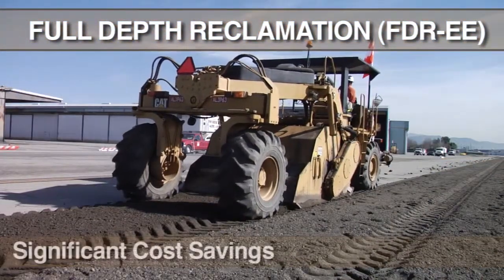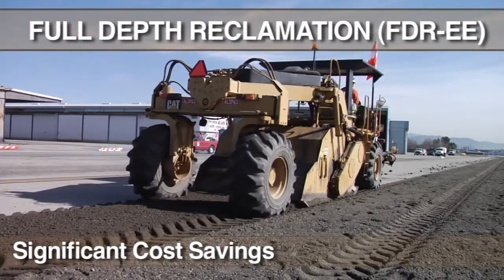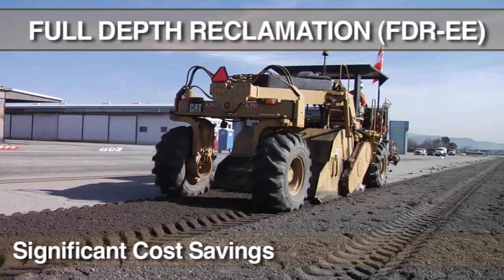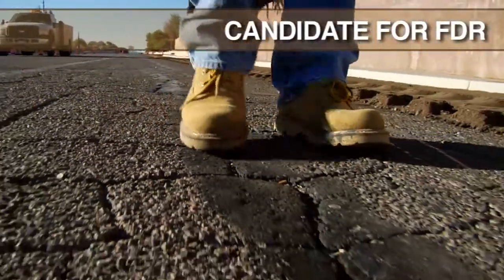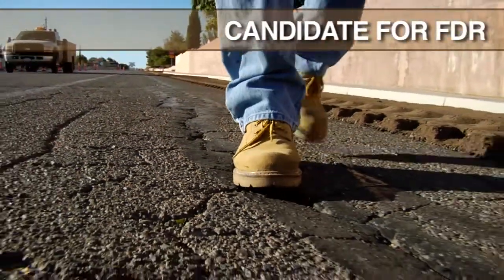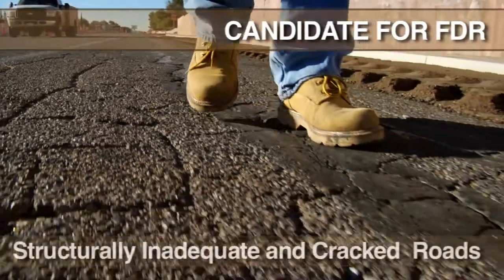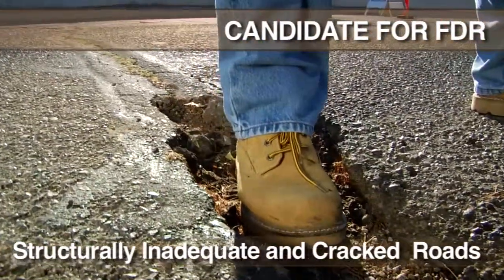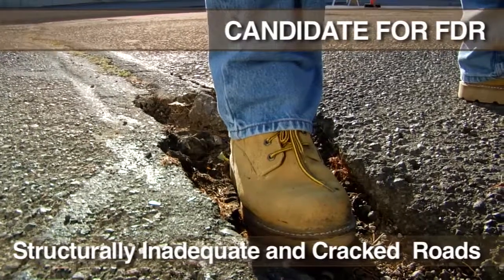Significant savings of 30 to 40% have been realized by many agencies when compared to traditional reconstruction cost. With this in mind, an ideal candidate for FDR are roads that are structurally inadequate and are suffering from cracks, potholes, and loss of bonding between pavement layers.